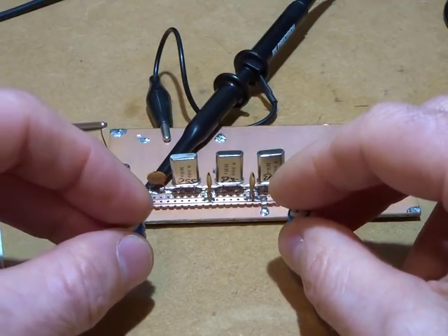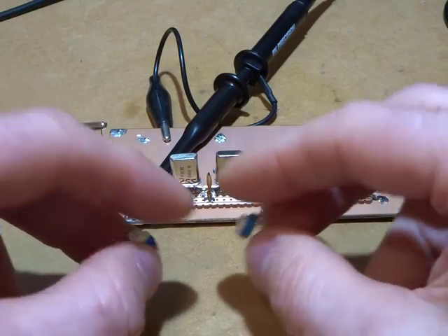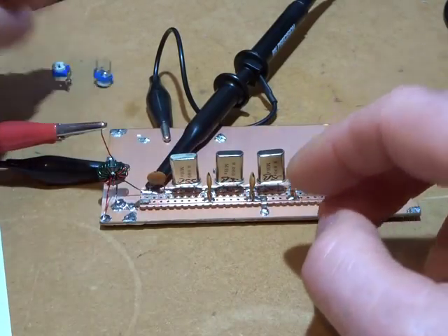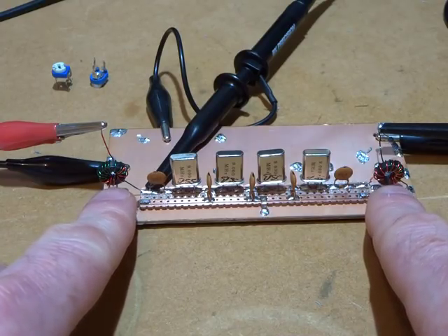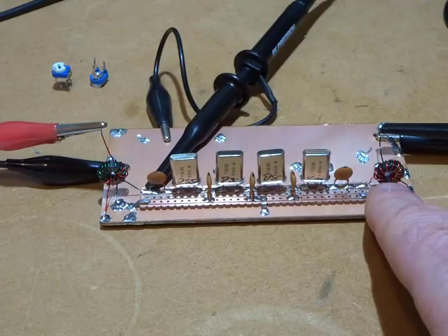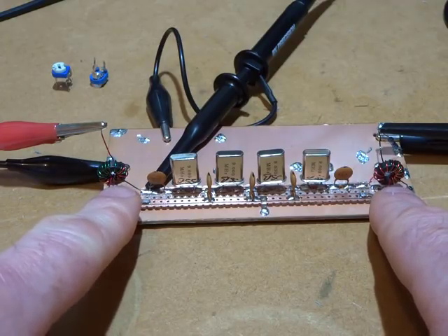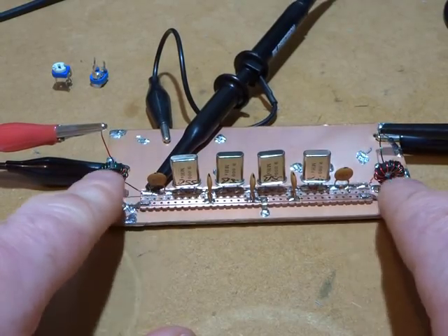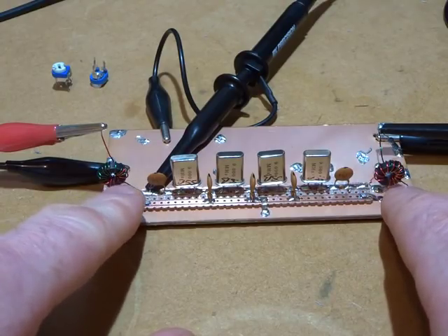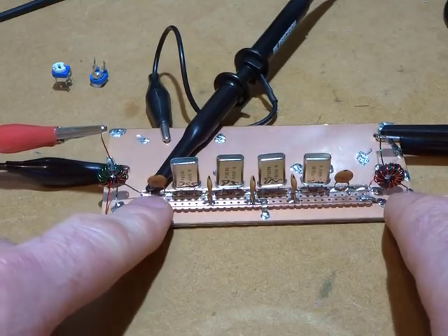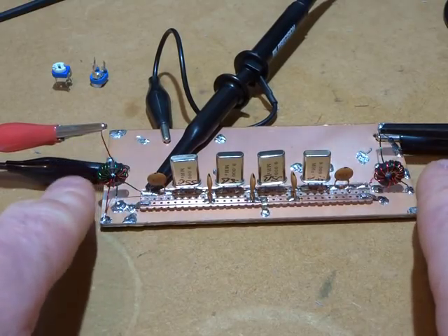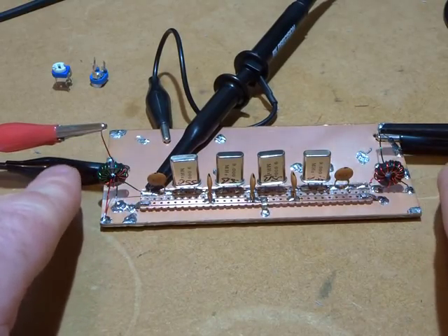In the end, I settled on 200 ohms, and I desoldered these, and in their place just used two FT37-43 transformers, out of junk boxes, which is why the different colours. The turns ratio on those is 12 to 6. So 12 turns on the secondary, or the side closest to the filter, and then 6 turns on the outside on the 50 ohm side.